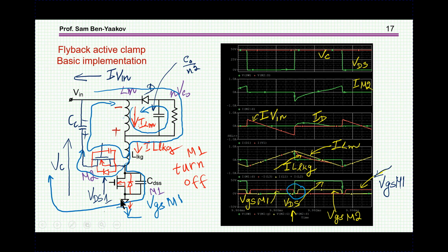As the red one goes down, this current, which continues flowing, of course, because this is an inductance here, will find a path through this capacitor, and then when this voltage eventually builds up enough, it'll go through this diode. So when this is off, we have these currents flowing, and here is the direction.